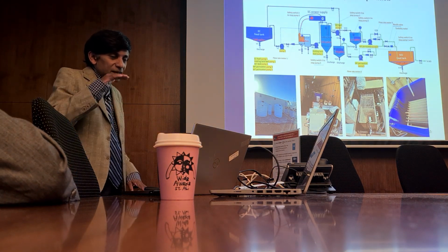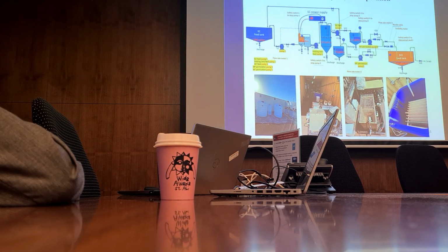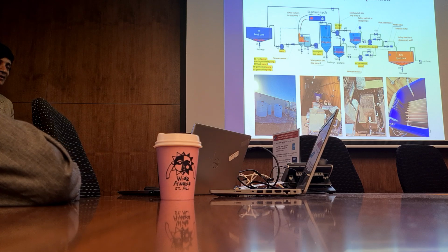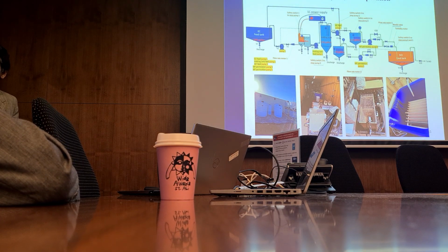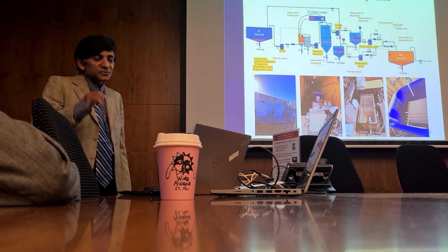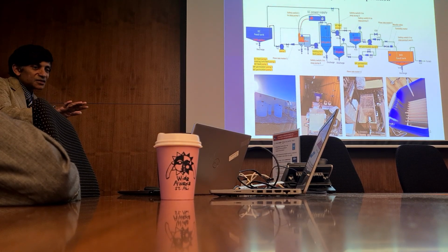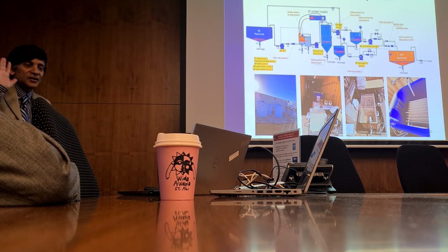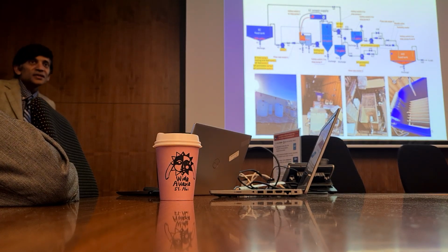There's another problem, and that is that the quality of the produced water varies a lot. Sometimes you got stuff that was over 200,000 ppm starting, which cannot be treated. It's almost impossible by this process. So the ones I showed you were about 100,000 ppm, which we decided would be the maximum that we would treat. The process we developed, with all the conditions in the paper, will work for 100,000 ppm or less. But more than that, it won't. You will get fouling of the membrane.